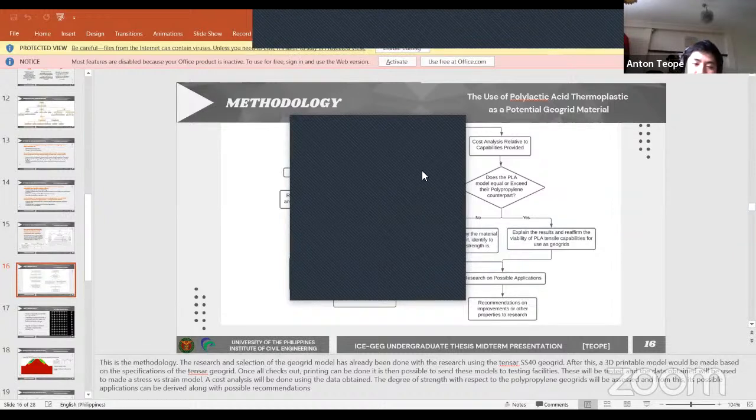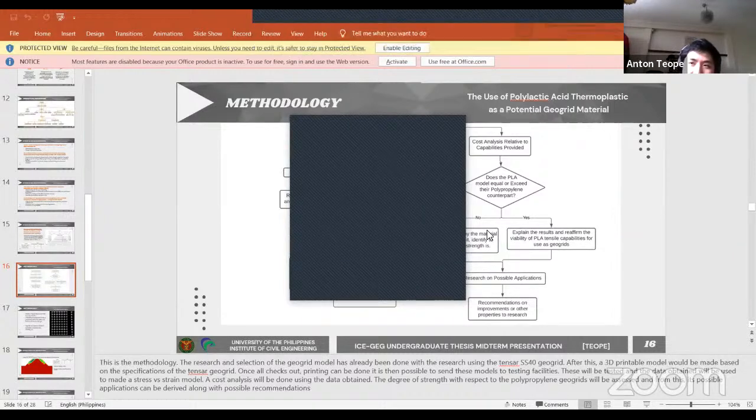There was no option of specific geogrid types. The only values that I could input were the stiffness modulus and tensile strength, which I varied to fit the Tensar geogrid, and which I would also vary to fit the geogrid which I have created using polylactic acid, and the cohesion values and bond friction angle.